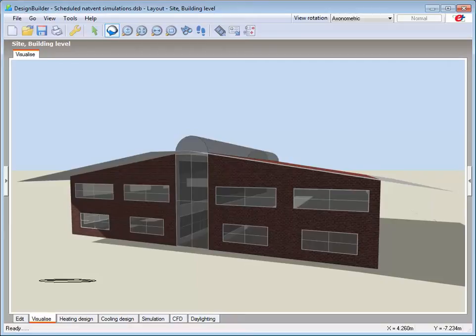Calculated natvent simulations can be used when you have no ventilation data for the building, but are more complex and take longer to set up and simulate. With the calculated natvent option selected, the ventilation rates are calculated using wind and buoyancy driven pressures, opening sizes and operation parameters, and crack sizes. These will be covered in the next tutorial.